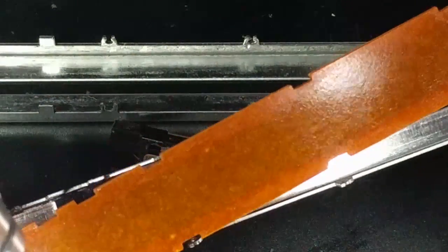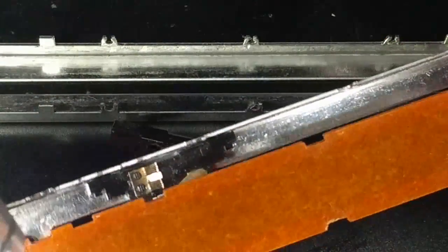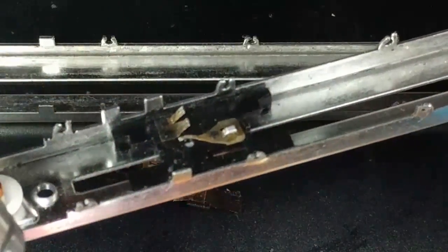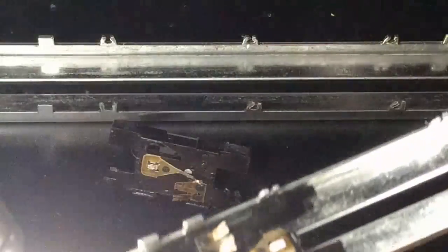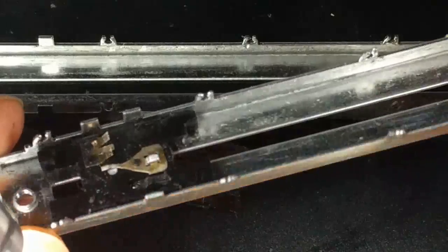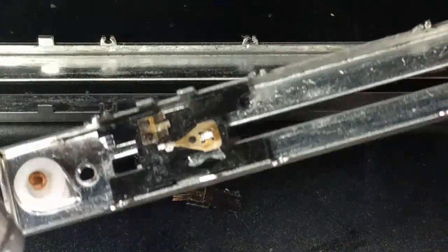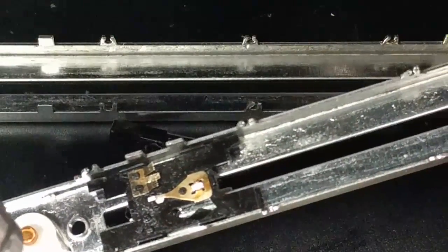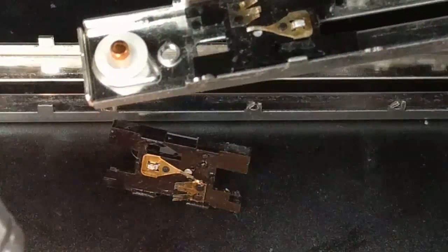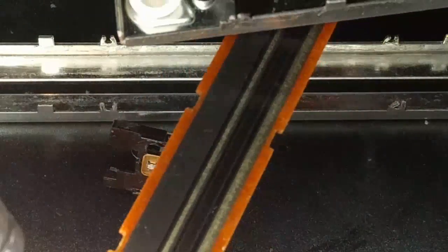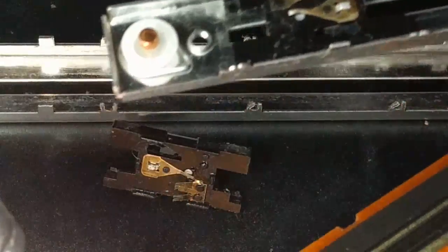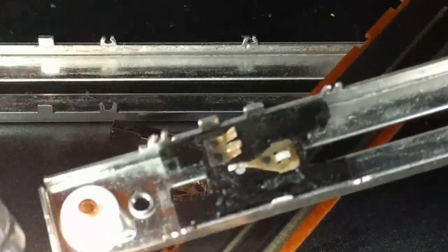Then I was, over and over again, reapplying this PCB on the top without the belt, just to do some testing with my clip leads, which I have hooked up to my multimeter, so that I could run this back and forth and see if the resistance changes accordingly. And what I found, to my great dismay, was that it wasn't, and I couldn't figure out what was going on. I thought the track was damaged, like the actual resistive element. It wasn't.